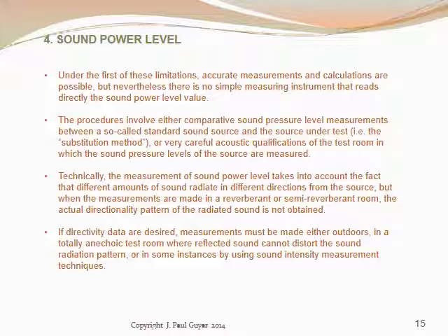However, when the measurements are carried out properly, the resulting sound power level data generally are more reliable than most ordinary sound pressure level data. With regard to the loss of directionality characteristics, technically the measurement of sound power level takes into account the fact that different amounts of sound radiate in different directions from the source.